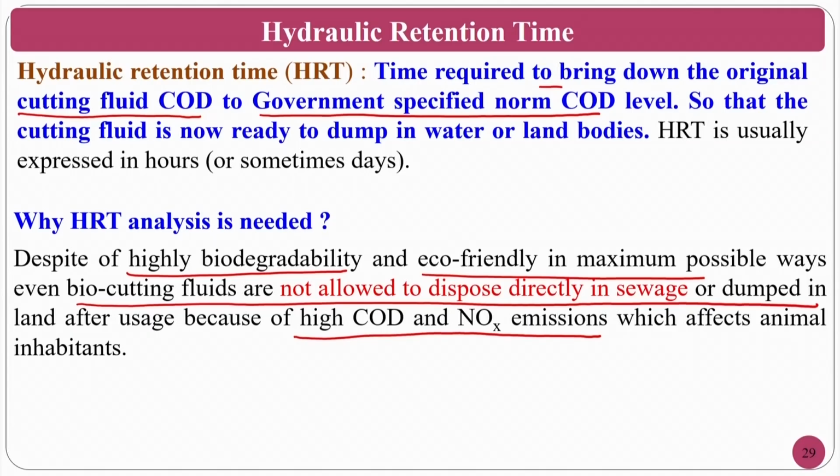Assume that even though it is biodegradable, your level is 500. In a biocutting fluid also you have to reduce it as per the government norm of 200, and then only you can dump. For that, you have to have a separate reactor in the factory, do the treatment, and then dump it. There is no problem.